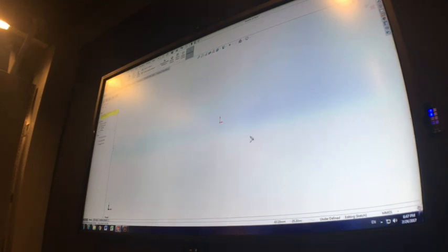So there's a quick and easy way to do this, so follow along closely. Now I'm not sure if you guys have noticed yet, but when you do sketch, when you move your cursor, there's a dimension that comes out with your cursor. You can see it on the screen there, it's 33, 39, 50. That's telling you how big your line is. It doesn't add a dimension, but it gives you a sense of scale. So if I want to get mine a little bit closer to scale, I can just zoom in, and now that's more about 10, 11, which is much closer to my end result.